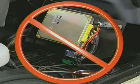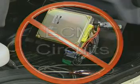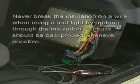Self-powered test lights should never be used on PCM or powertrain control modules and electronic control unit or ECM circuits, as the high current flow will damage those units. Never break the insulation on a wire when using a test light by probing through the insulation. Circuits should be back probed whenever possible.